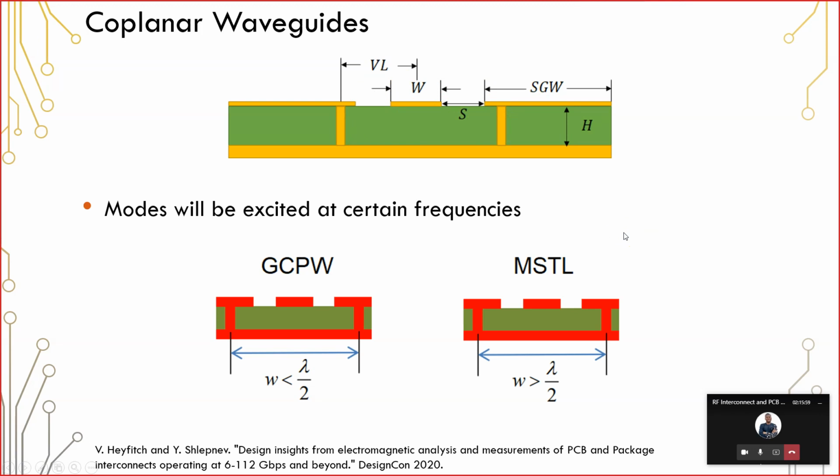So if you're operating at Wi-Fi frequencies, the main reason that you use a coplanar waveguide is because it gives you some shielding with respect to other circuits in the system. If you look at any system that uses Wi-Fi and it has to route a signal into an antenna, there's going to be other stuff on those boards. There will be some kind of embedded processor. There might be some kind of DSP, some kind of application processor or something like this. So those are going to exist somewhere on the board. And you need to make sure that you shield your RF frequencies from those other portions of the system.